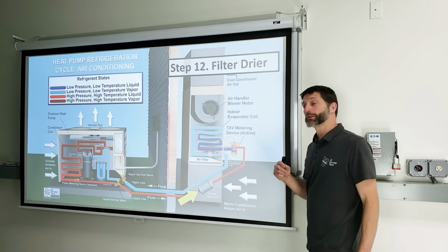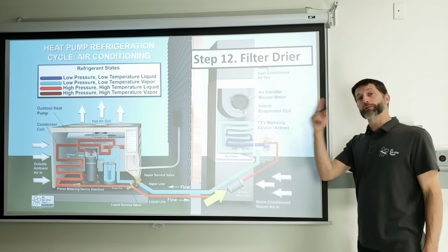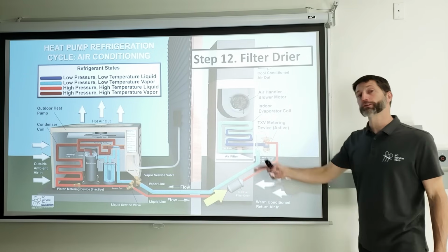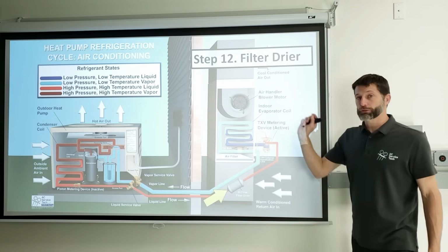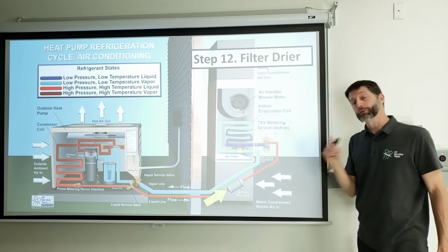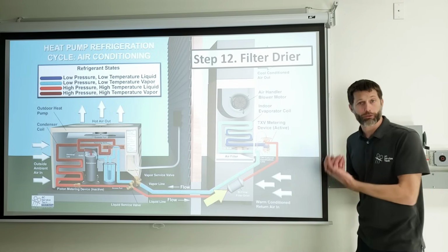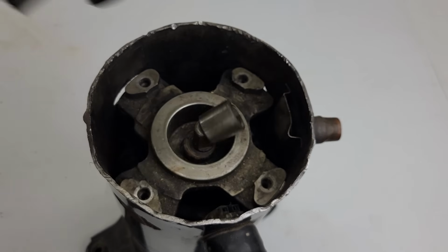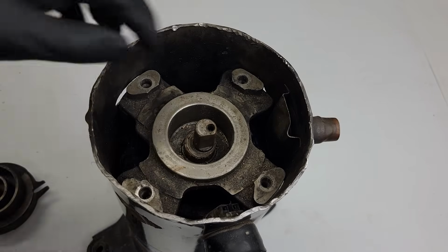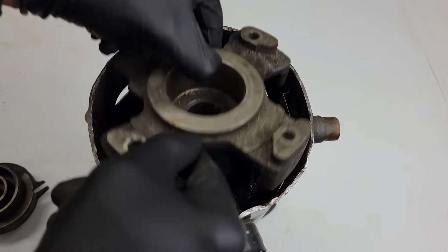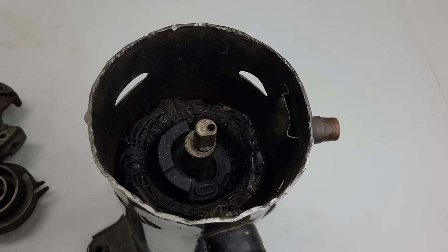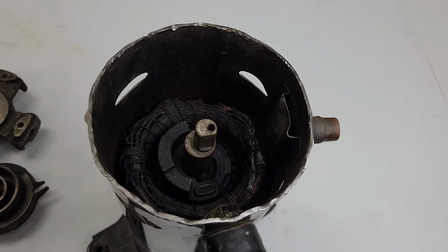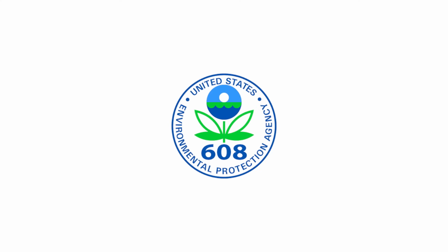When that happens, you also have to remember that the refrigerant is flowing through the entire system, and the refrigerant is traveling into the compressor. Refrigerant and oil travel together through the system. And that scroll compressor is a hermetically sealed compressor. That means it's a welded shut compressor. Once again, that's a fancy word, hermetic compressor. It's on the EPA 608 exam.